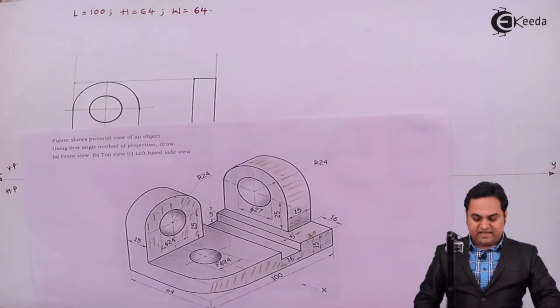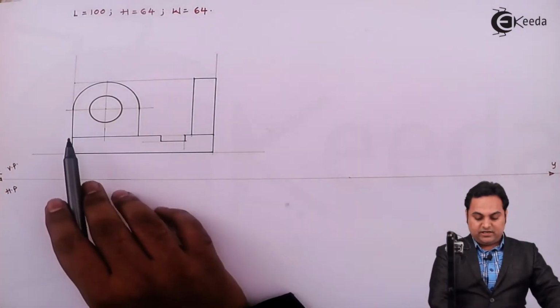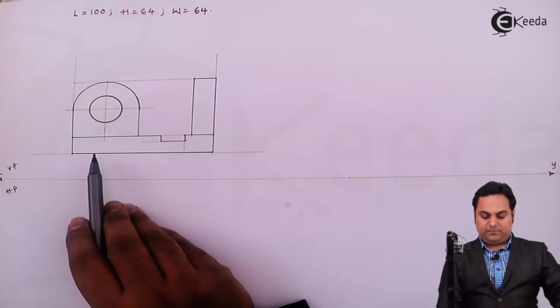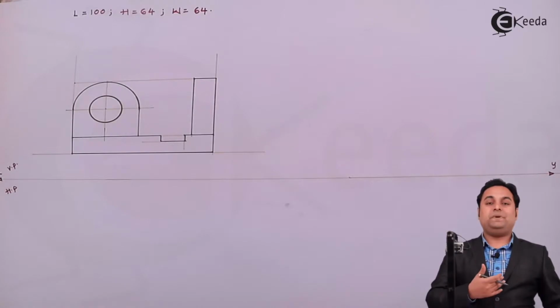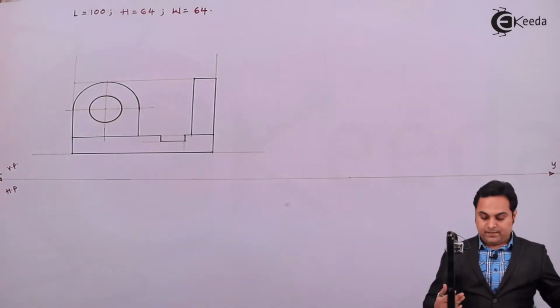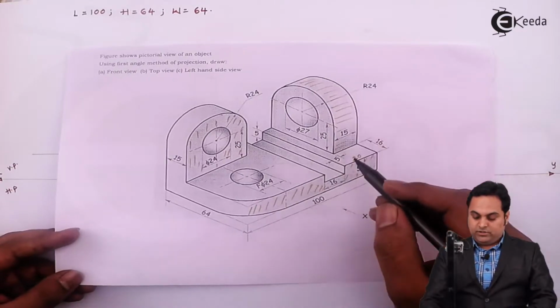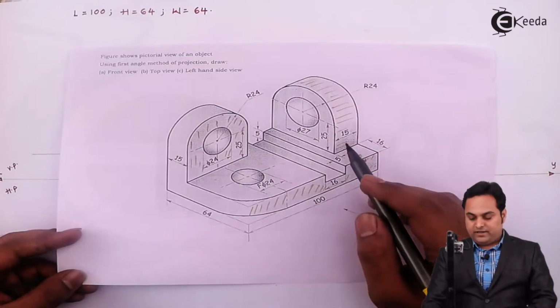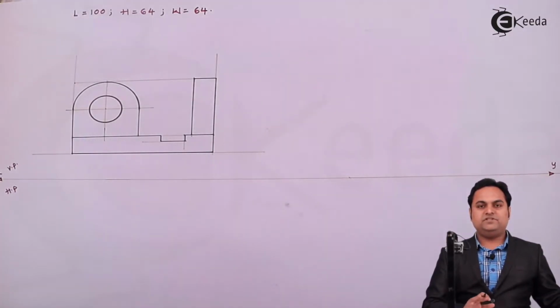So in this diagram which I have drawn, there is a dark line between the semicircular part and this plate, which indicates that there is a change of plane. One part is ahead, the other is behind. Next, similarly, for this semicircular thickness and this block, again there will be a change of plane, so there is a dark line between them. This much is the visible portion.